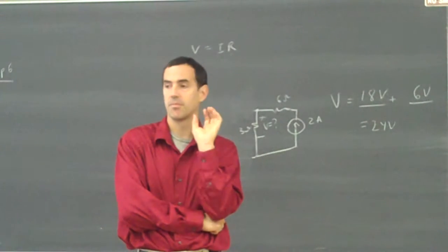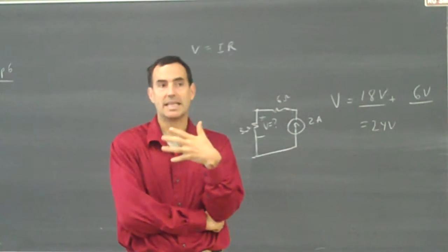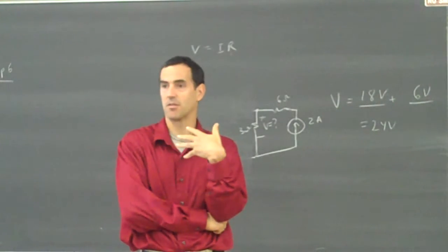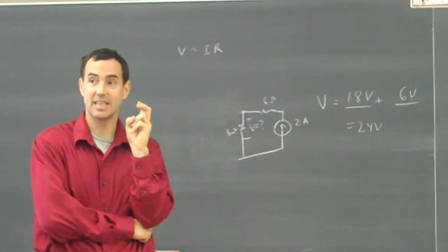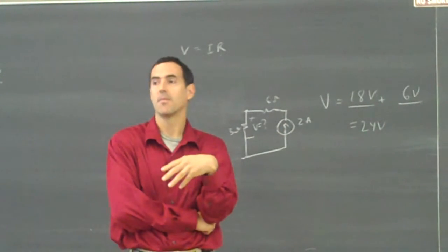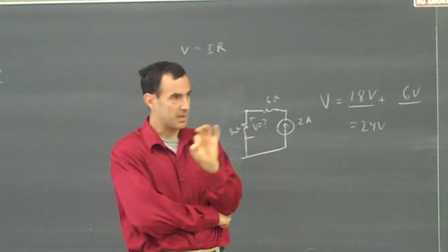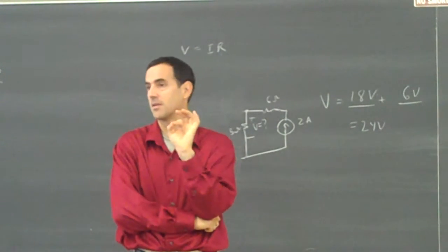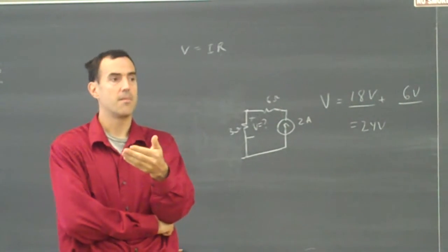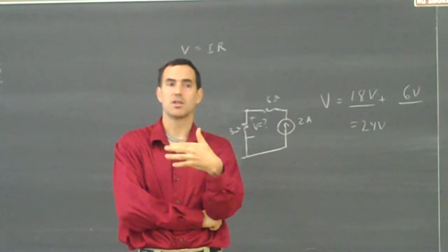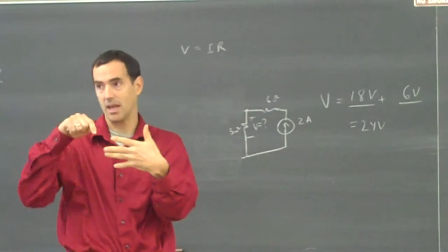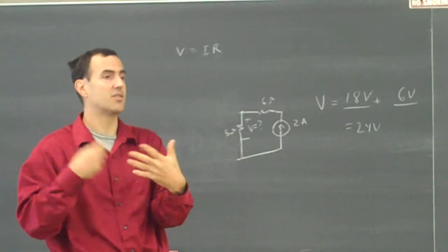In fact, some LED displays, some of you may have on your phone, mine doesn't, but mine has an LCD display, liquid crystal display. Have you heard that term? So you might have an LED display. The LED lights up the individual dots on your phone by putting a steady current through it for a certain amount of time. So I want a controlled current. That produces the light. Applying a fixed voltage would make it much more non-uniform brightness for that screen. So those screens rely on having a fixed current through each dot. The individual dots are called pixels.